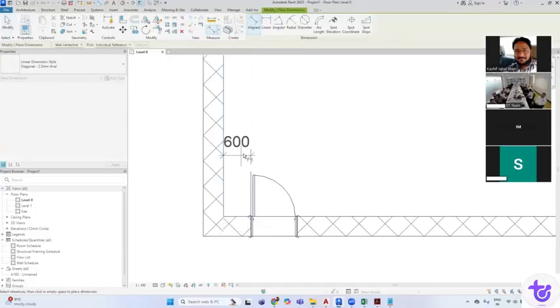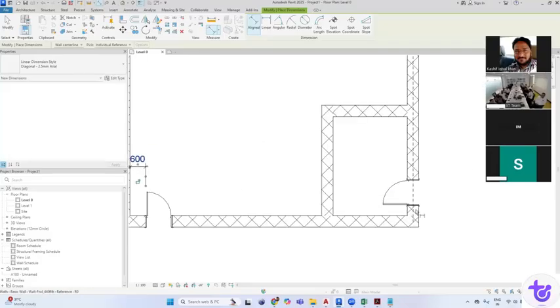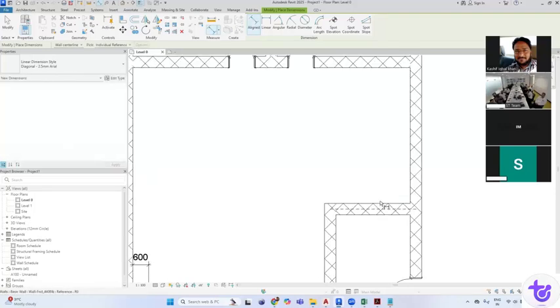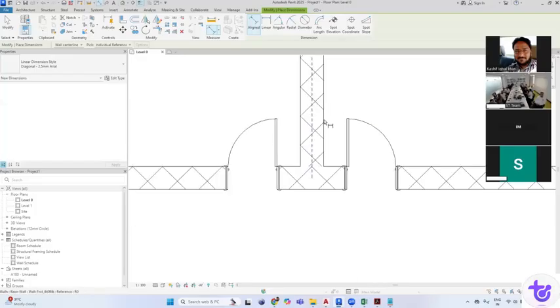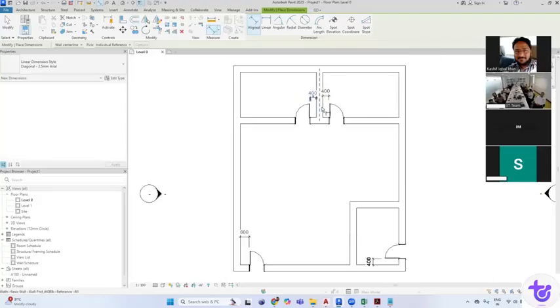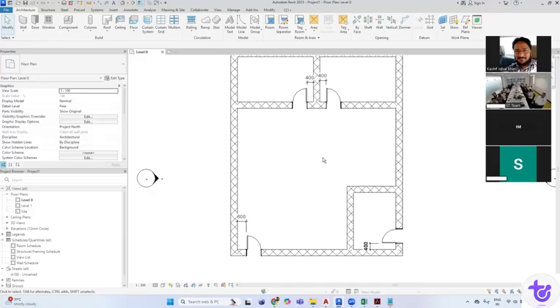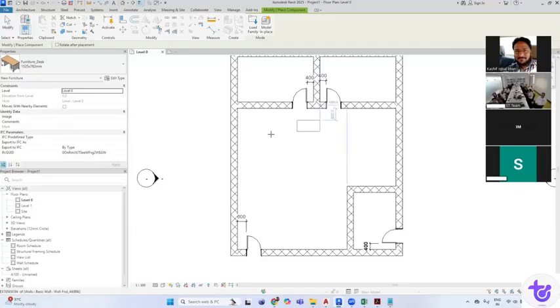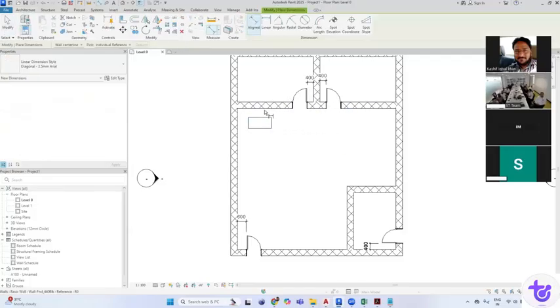What if we want this offset of the door from the wall to be consistent? It can vary from project to project sometimes. If we fix it with a lock constraint somewhere, there is a chance it is changed based on design decisions. One more example: we'll take some furniture item, maybe a bed, or for now a table, and we want to keep some distance from the wall face.